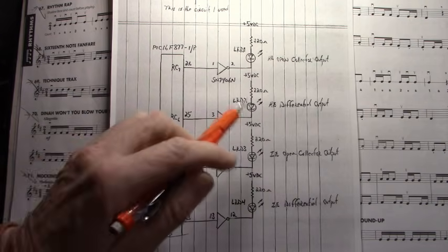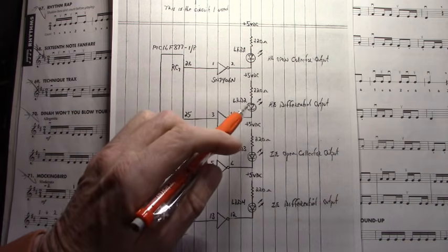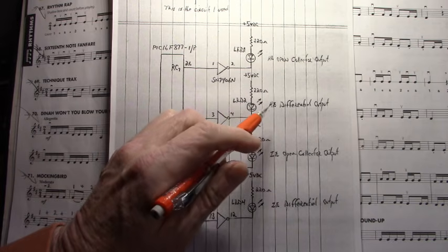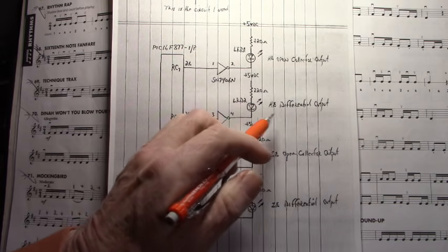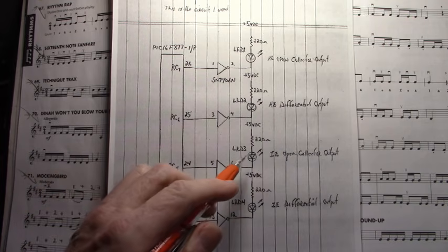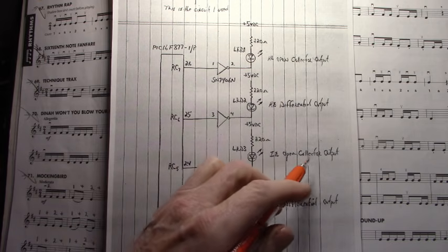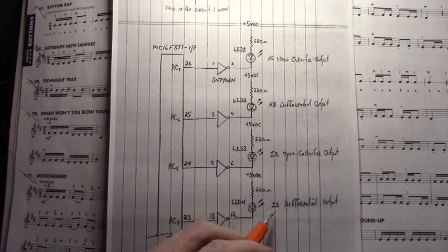The same down here on port C bit 6, that turns on this LED right here, which indicates to us that we would be differential output on the Hall effect pattern. Port C bit 5 turns this LED on, where we would be open collector output on the incremental encoder pattern. And RC4 on pin 23, that turns on as well as turns off this differential output in incremental encoder pattern.